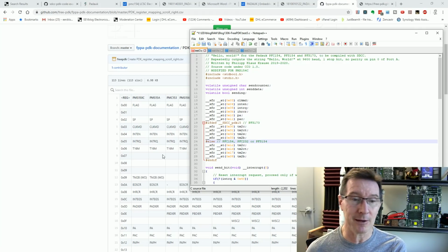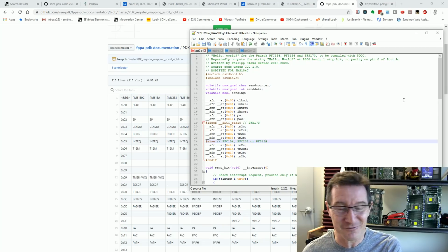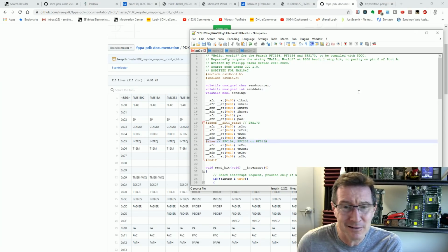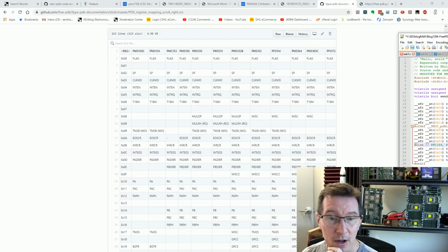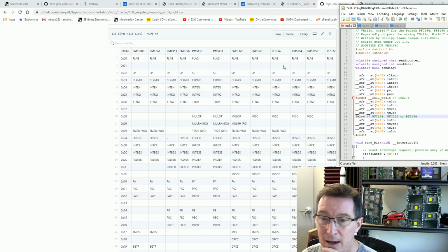And hopefully we can get our program working, because what's actually causing that weird fault? I can only imagine it's getting an interrupt from a floating input pin somehow. Well, no, I'm actually comparing all this stuff here between the PMS and the PFS154, and they're all the same.